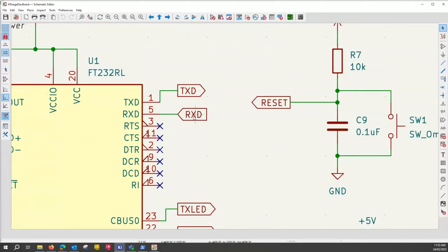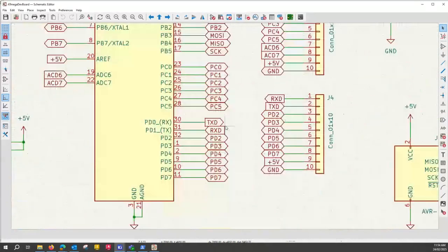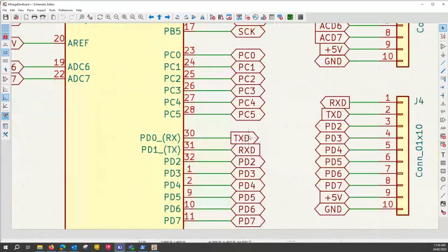Receiving pin number 5, we marked it RX. And if we look at the microprocessor, our transmission from the FTDI chip comes into the receiving pin of the microprocessor, and then its receiving pin comes into transmission, because you've got to have them crossed like this. Which means that technically you can name those whatever you like. You could name it TX-RX and this one RX-TX, to indicate that this is communication left to right and this is communication right to left. Whatever you want to do, it's fine.